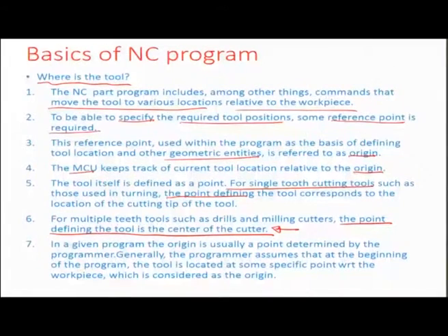in the job of a programmer. So, there are certain machines which would typically have a command for tool compensation, but in a vast majority of cases the programmer may need to actually account for that radius, and he may consider himself to be sitting in the center of such a multiple teeth cutting tool, where he is trying to map his own movements with respect to the workpiece as machining is carried out. So, that is another important aspect for a programmer to know.